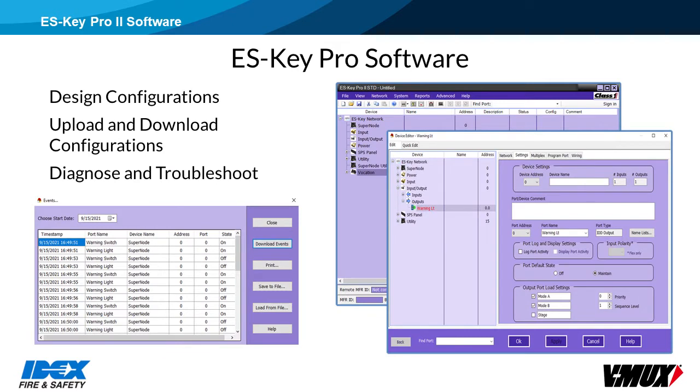The S-Key Pro 2 software is a desktop or laptop application for the custom configuration of the electrical systems of emergency and industrial vehicles. The target vehicles are designed and built around a CAN bus network containing a variable number of S-Key modules that, to simplify, control inputs, e.g., switches, and outputs, e.g., lights. At the core of each vehicle network is a Universal System Manager or supernode that implements the configuration created using this software. A modem, a serial, a USB interface module or a USB cable can be used to load new configurations, diagnose and monitor system activity.